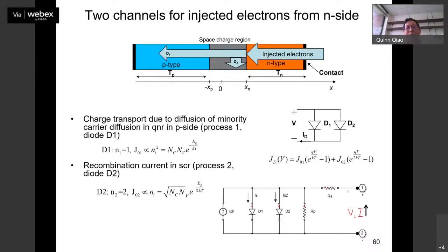Sometimes in the light IV characteristic, we are seeing two slopes. One is in between the JSC and VOC, when the current is positive, and it is giving a different slope in the light IV characteristics. So what can we conclude from that? That one, many times, is not the diode. Many times it's because you have huge defects, huge transport problems. And that problem is associated with the bias, not the photogenerated bias, but the different bias that drives transport, for example the diffusion, just an example here, D1, D2, right? The D1, D2 are also determined by the p-type material quality, and also the p-n junction quality, right?